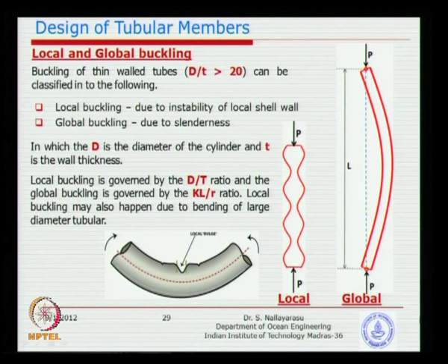Or sometimes if you have large bending, you may see that local buckling becomes a problem at a particular location because of this kind of local bulge failure, which is potentially possible. You take a piece of paper, roll it into a small tube, and try to bend it, you won't be able to bend even a few millimeters, because the wall thickness of the paper is so thin that the central portion will bulge out and fail in bending.